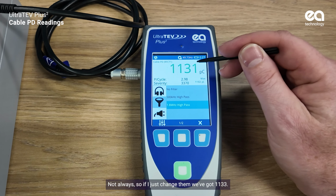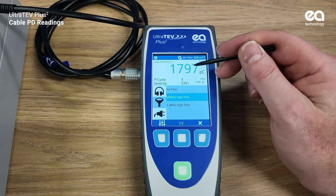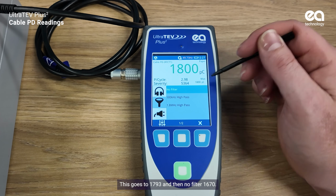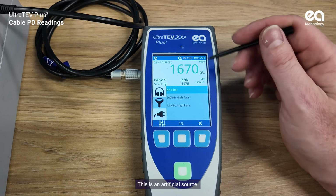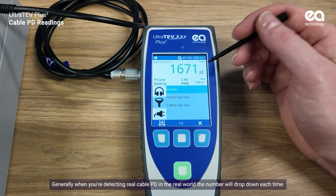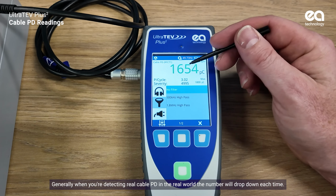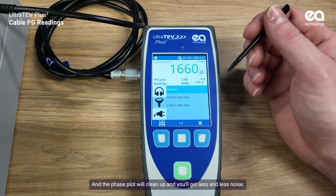So if I just change them, we've got 1133, go to that one. This goes to 1793, and then no filter, 1665. This is an artificial source, so it's just the way that source is behaving. Generally, when you're detecting real cable PD out in the real world, the number will drop down each time and the phase plot will clean up and you'll get less and less noise.